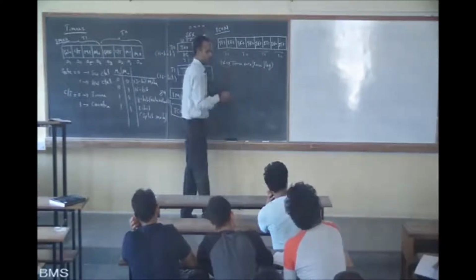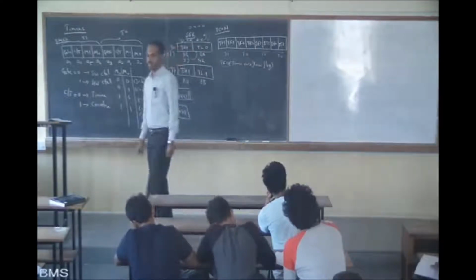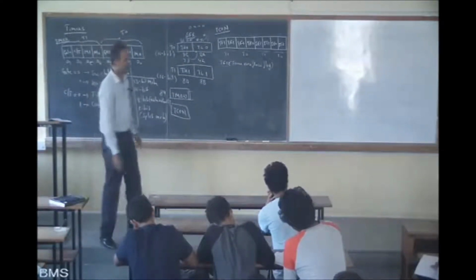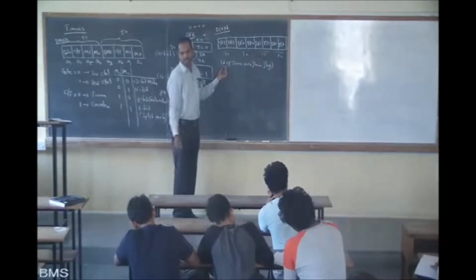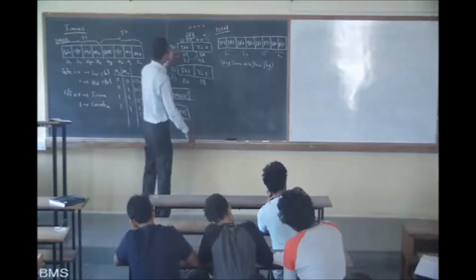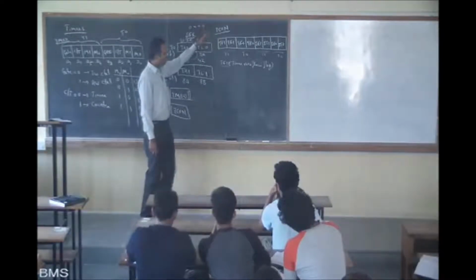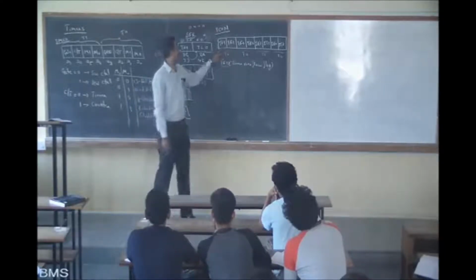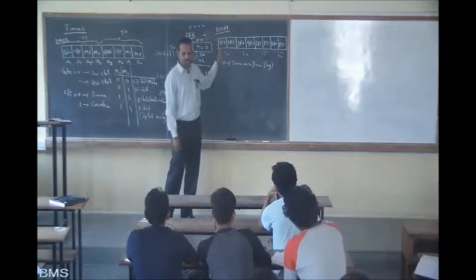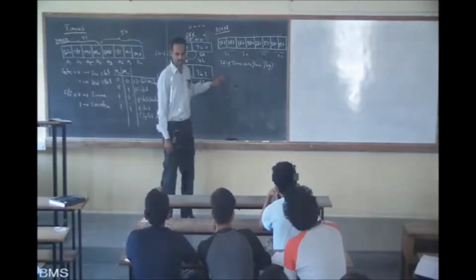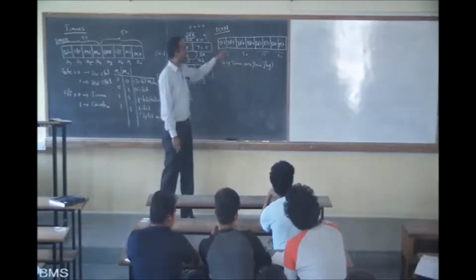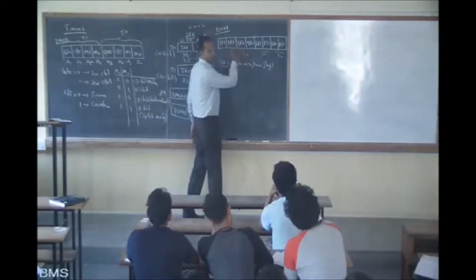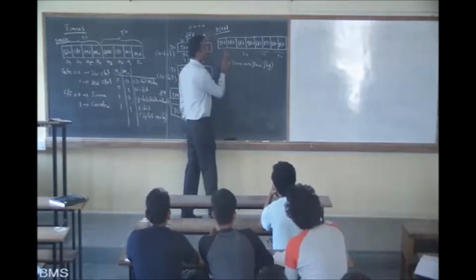Below that, write: it is hardware set, software clear. What is the meaning of this? It is set by hardware by itself. The 8051 structure is such that when the timer reaches its maximum value and goes to the next minimum value, the flag sets by itself. That is hardware set. But software clear means we have to clear it. We have to write one instruction in the program to clear this. How do you write it? CLR. SETB for setting it, CLR for clearing it. If we use CLR TF0 or CLR TF1, it will be cleared. That is the software clear. TF1 and TF0 follow the same concept; one represents timer 0 and the other timer 1.